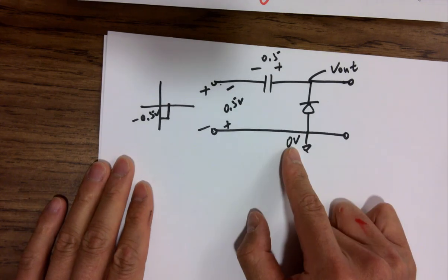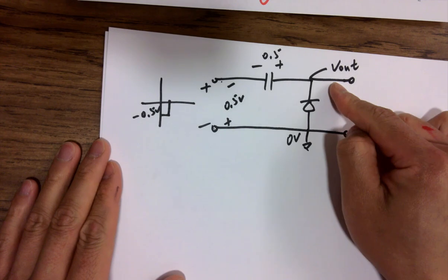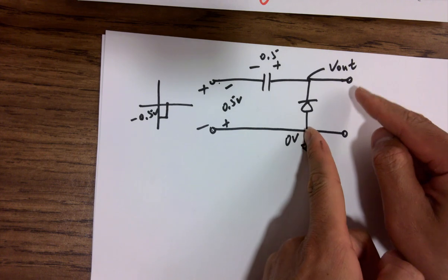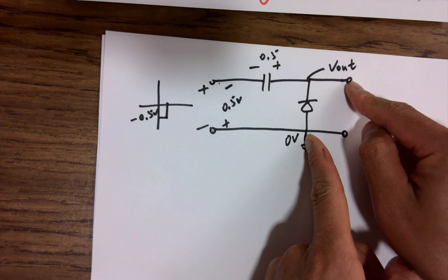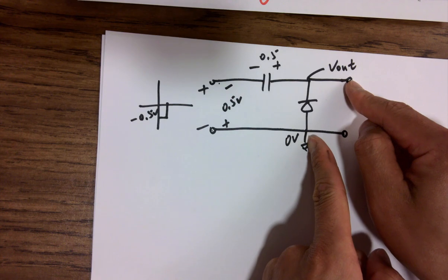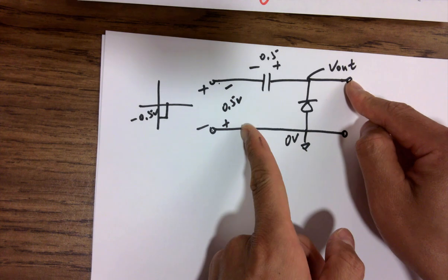So you start from the reference. When I'm talking about what's the voltage here, it's compared to ground, right? If I have a multimeter, the black probe is over here, the red probe is over here. I'm probing these two nodes, right? So you only need to tell what's the difference between these two nodes. That's it. You guys are seniors. So where's 0 volts? Here, right? So 0 volts, I already labeled it.